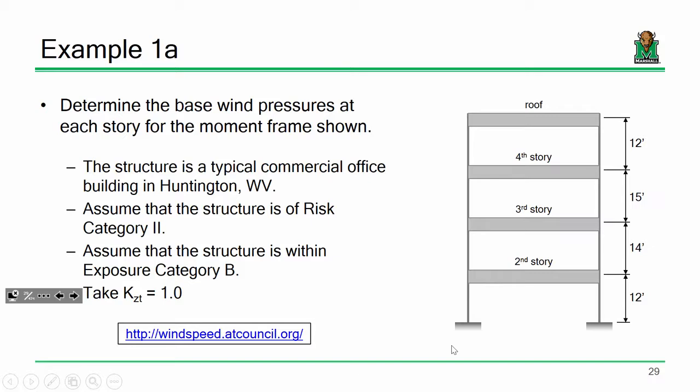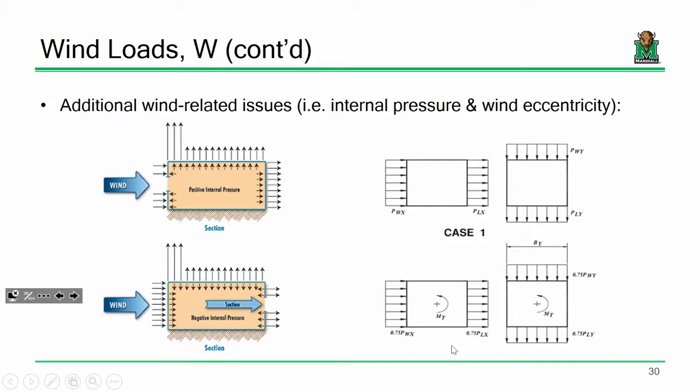So we went and did a pretty basic example to try and assess how you would compute base wind pressures at varying heights of the building. What you would then do with those pressures is similar to what we did in concrete design, regardless if you had it last year or 2 days ago: we would take that wind pressure and distribute it across the element's tributary area to determine what's the point load I need to put on my RISA model or what have you. And we're going to do something somewhat similar today with seismic.